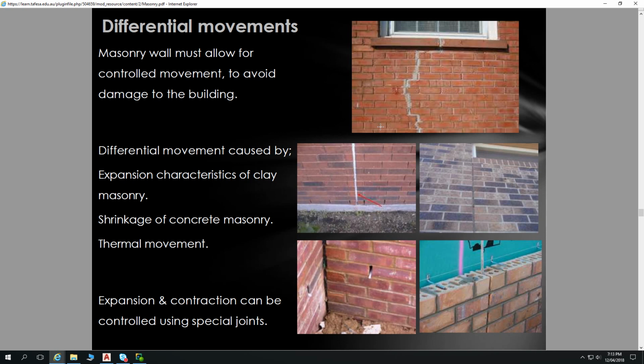But in modern buildings, to ensure that we don't have that happening, we have these brick control joints that happen at the sides of openings, and if it's medium class soil, then it's every 6 metres. If it's reactive soil, then it's every 5 metres, typically. So refer to your AS 3700 for that.